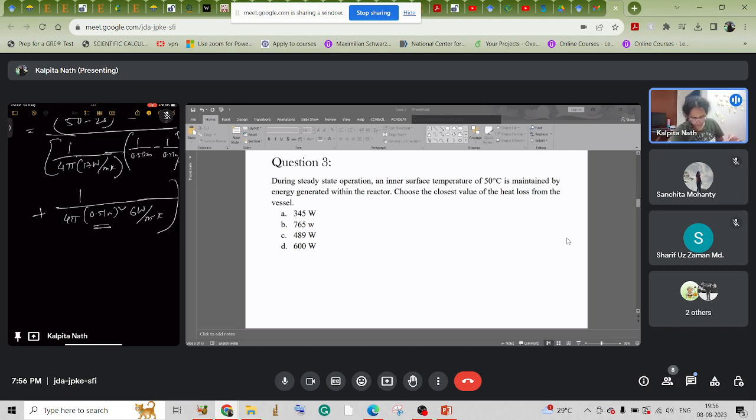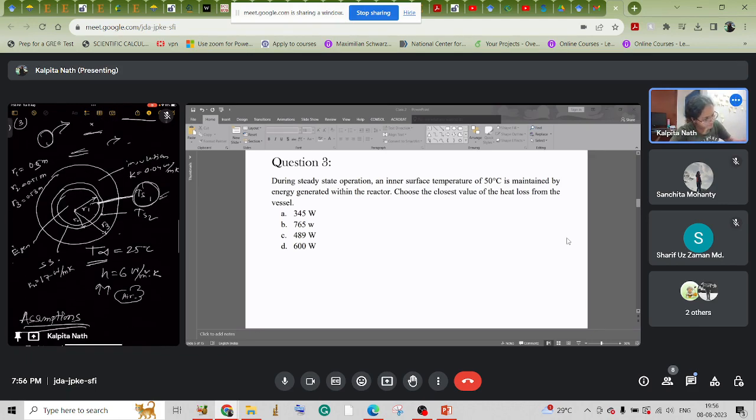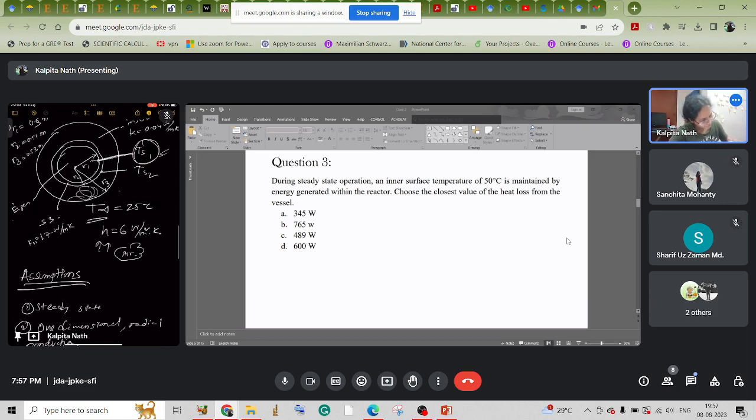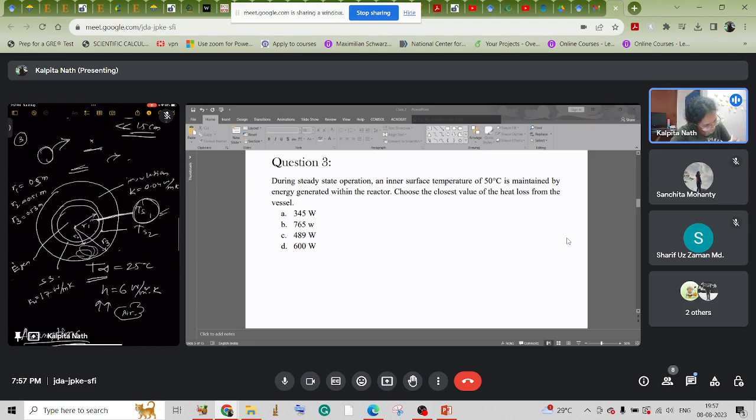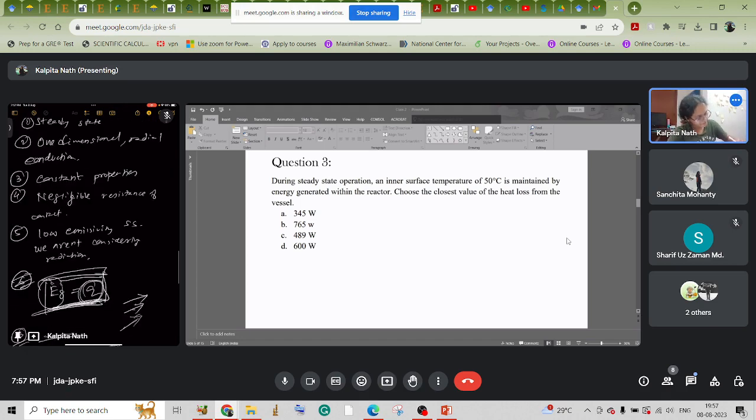Okay, so now this is the outer radius, because in the first case, again I'm saying, no insulation is considered, so we won't be considering this whole insulation. So there are two radii we are considering, first 0.5 and then with the stainless steel thickness, that is 0.51 meter. Don't get confused. So here TS2 is not even present, because the outer surface of this stainless steel is itself in contact with the outer atmosphere. So here TS2 doesn't come into the picture.